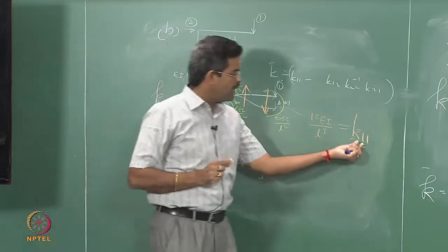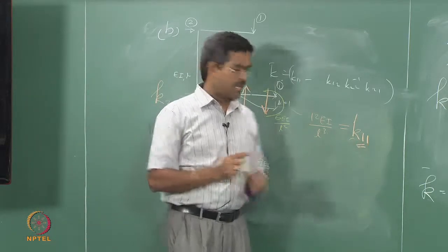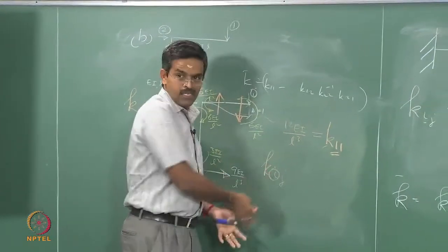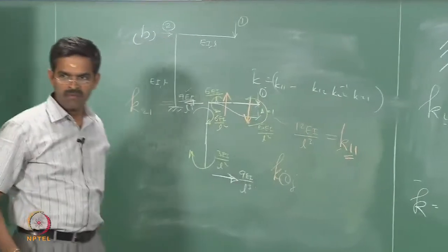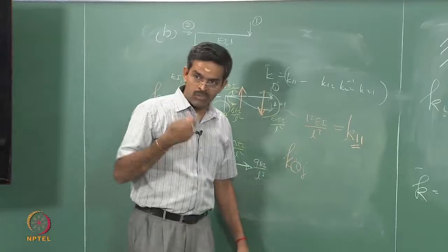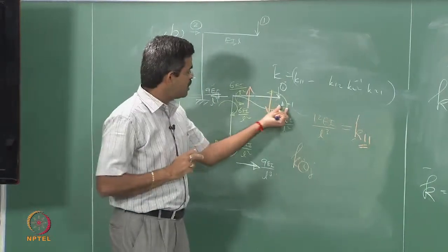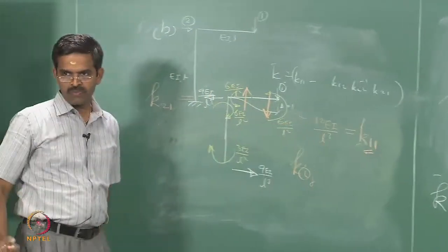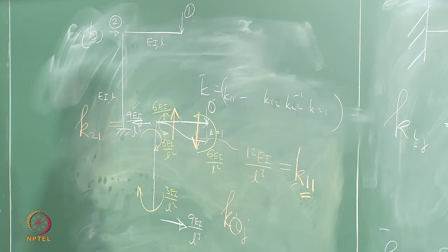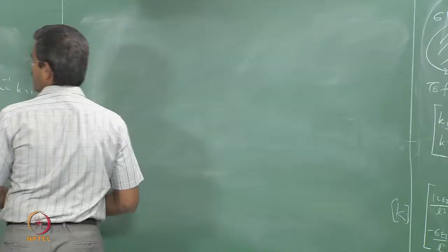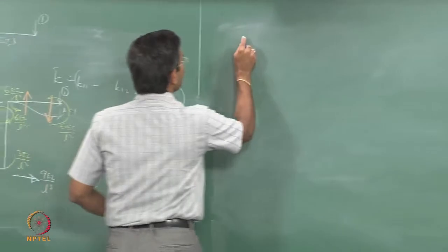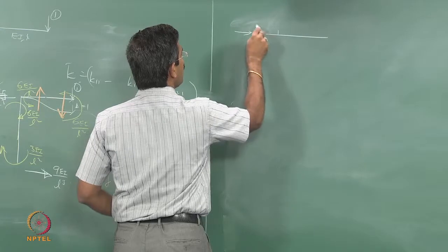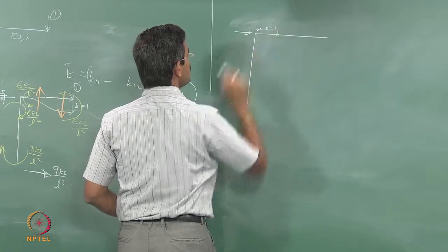This is the force in the first degree, displacement given in the first degree. Kij is the force in the ith degree because of displacement given in the jth degree, keeping all other degrees constrained, and that displacement is unity. That is how you get stiffness. Therefore, it is unity, and in the whole equation delta goes away; there is no delta here, you see. The delta is unity, I have removed it. Similarly, let us give displacement of 1.